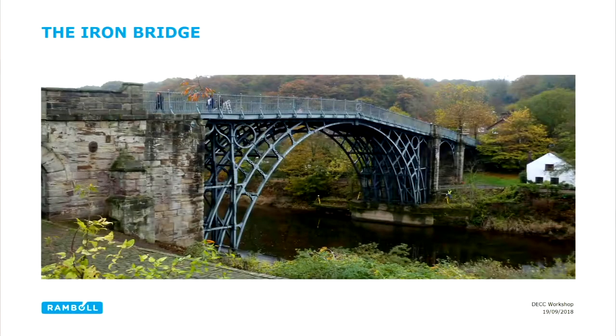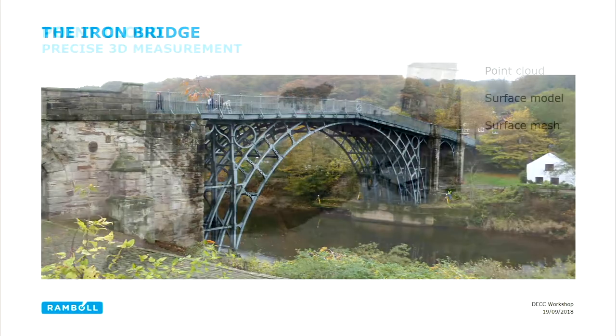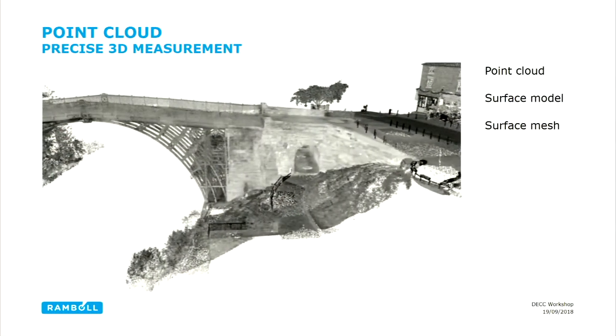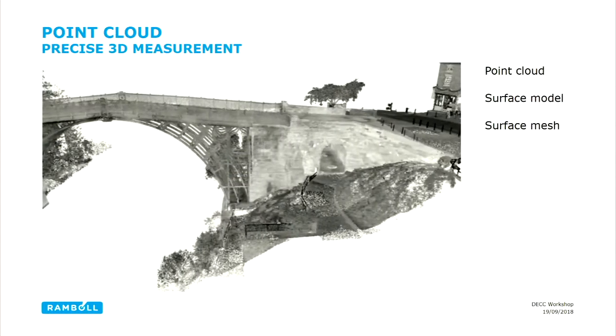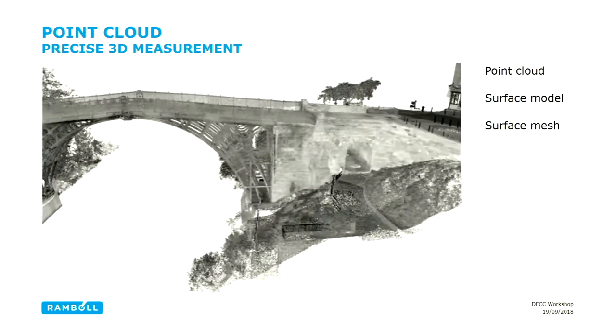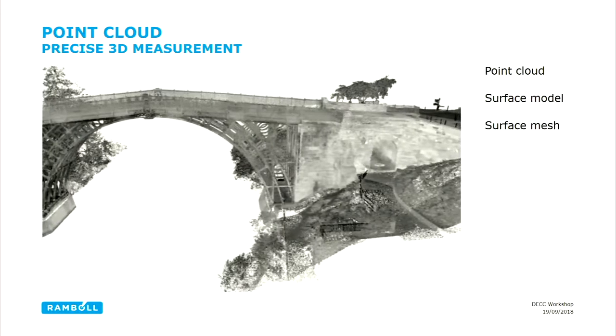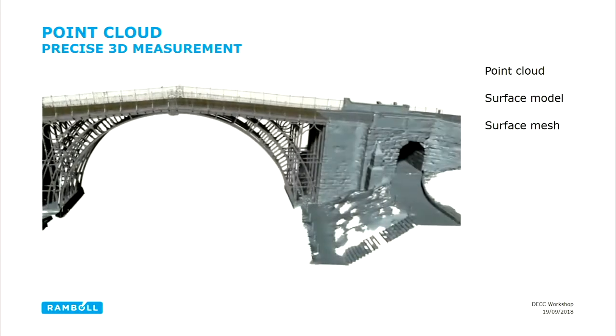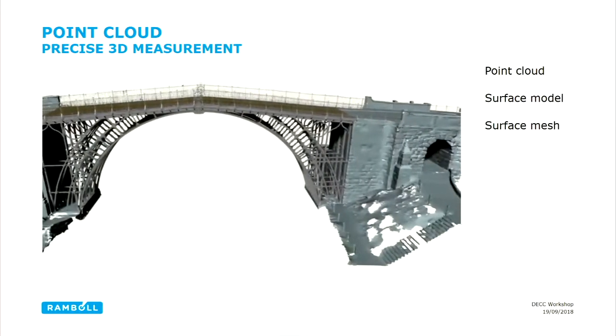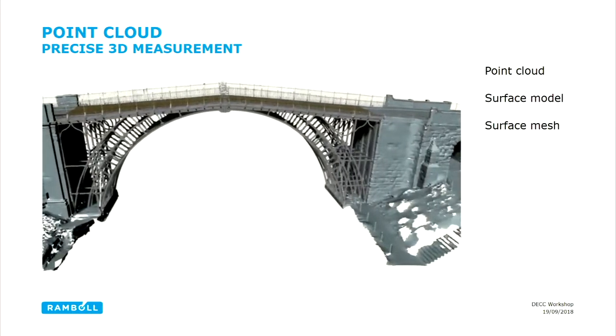And a more recent example of working that way was when we were asked to do a strength assessment of the Iron Bridge. And so the first thing, again, is we need really good quality geometry. The specification for this was to aim to laser scan it with a terrestrial system, 95% coverage, ideally 2 millimeters, something like that.